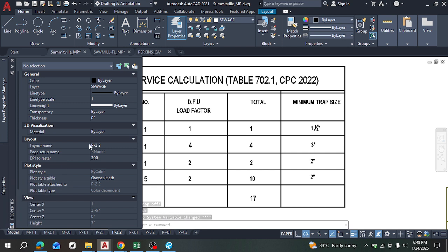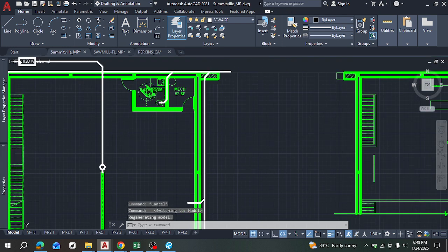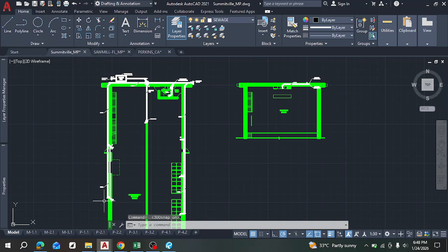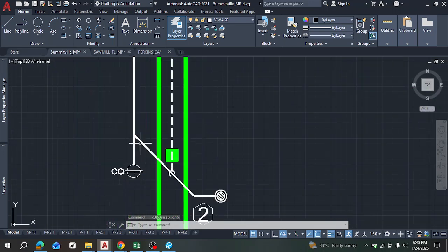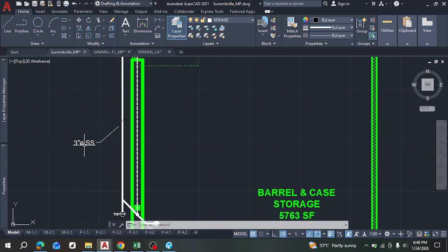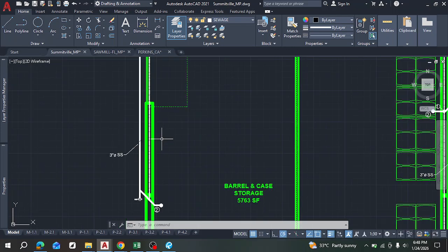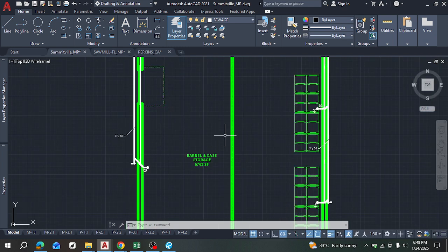Now let's complete that. Let's just add all the necessary details, and now it looks like this, right? So we've added our clean out here, so you see that it is not in the direction of flow, it is opposite the direction of flow. It goes this way, then the clean out is out here, right? Then we have our, I mean, this could have been 2, but just leave it at 3, being that it is outside, it could get frozen. 3 is just a safe value.